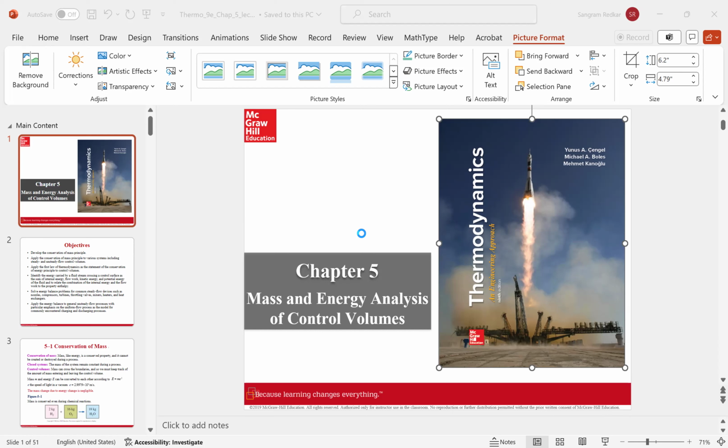Now, it's again very important. I'll give you a very simple example. If you have a fluid flow and you put a block of wood in the flow, you will notice that the wooden block moves, which means there is some work done. That work done is nothing but the flow work that is needed for the flow to enter the control volume and to exit the control volume.